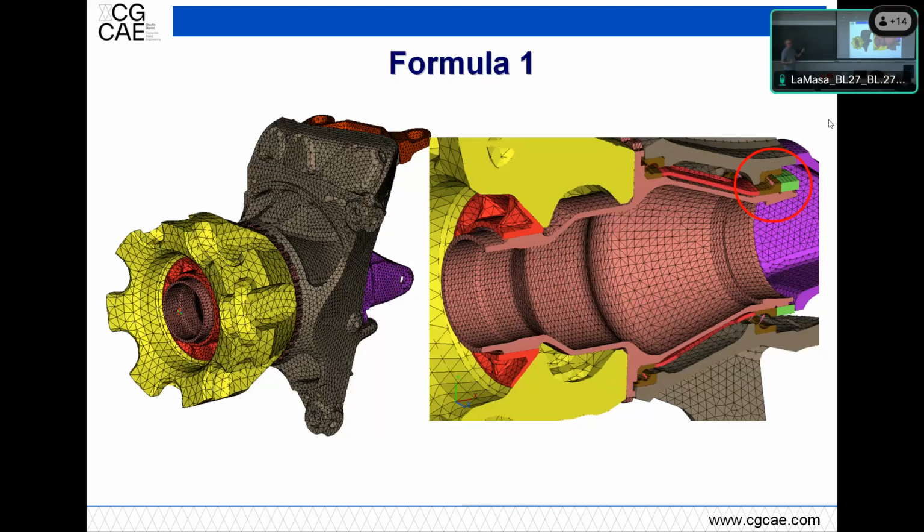Before starting this whole process, Rory Byrne said, okay, we take an old upright, which at the time were made out of titanium sheet metal, so welded. And you tell me where to place some additional plates to stiffen it up. I could only reach 10% more, which was already something. And then they went to test with Schumacher in Fiorano, only on the rear.